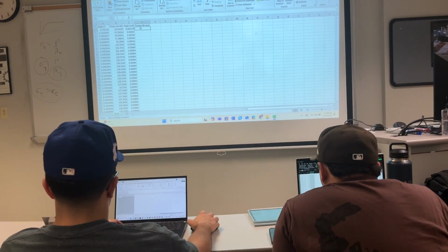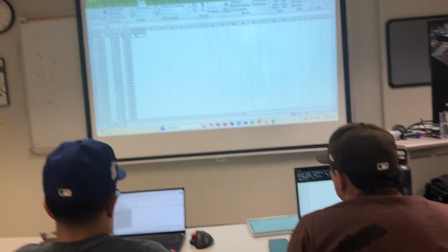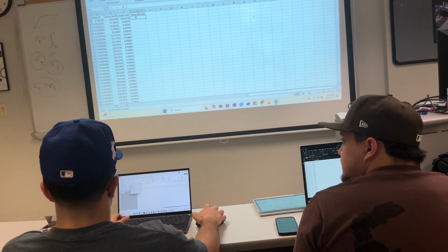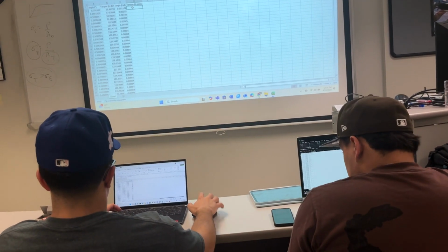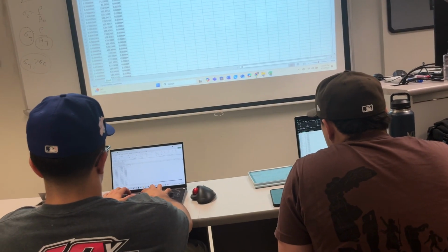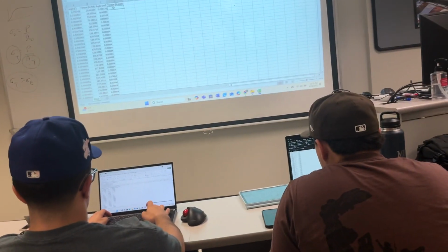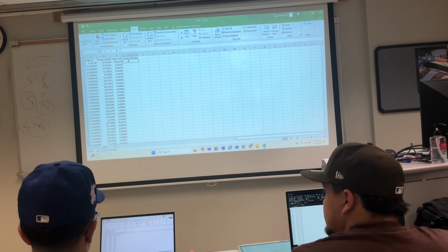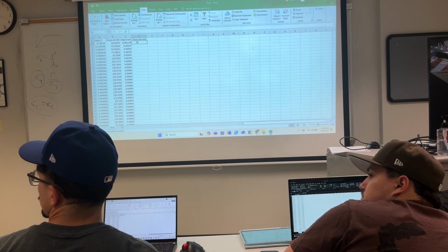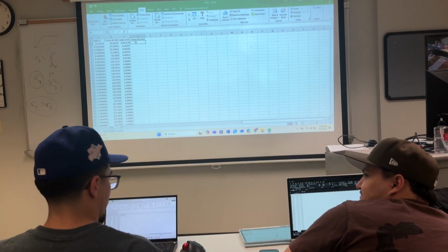Yes. Okay, so this is basically a force, and this is your distance. So 1 LBF you have to convert into Newton, and 1 LBF is 4.4482. And 1 inch is 25.4 mm. So your torque will be 4.4482 multiplied by 25.4.